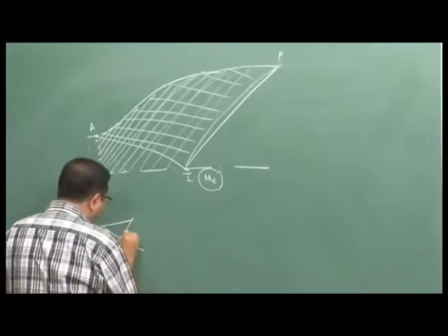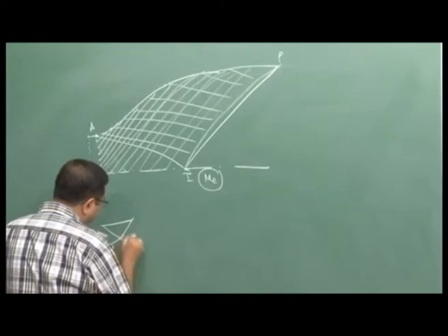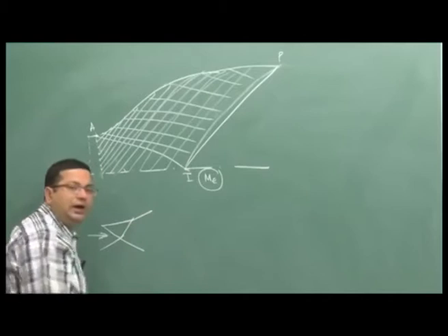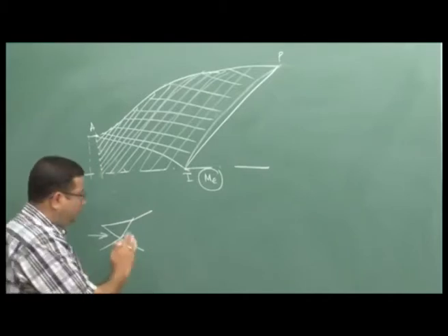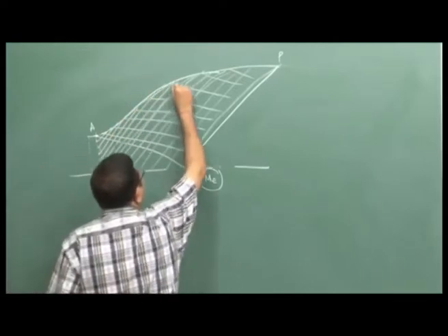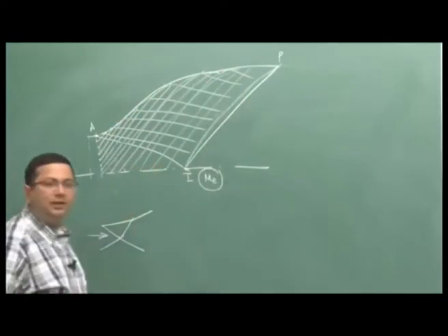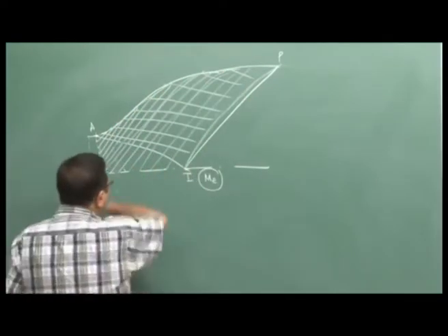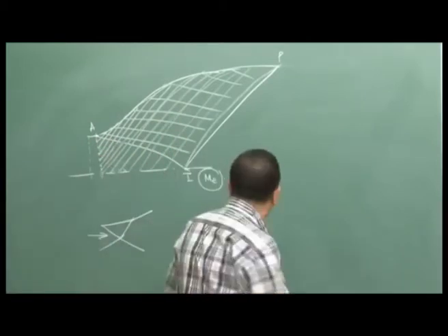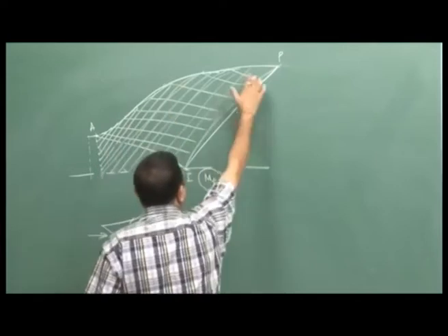Then we have crossing of Mach lines. Based on that we can get the conditions here and how much turning is required to get parallel uniform flow. That is how we solve for this entire contour. So, by doing this we can solve for a two dimensional flow field for the entire nozzle.